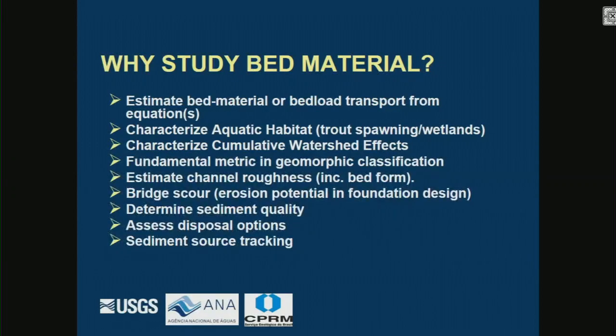So why would we do that? Here are a number of different reasons. The main one I run into is the very first one, to estimate bed material or bed load transport from equations. A lot of the different models, the main driver is the bed material sample, and usually it wants a particle size distribution of that bed material. So it's fairly important. The bed material is the input to the model. Then you run this model, and it tells you what the transport is.